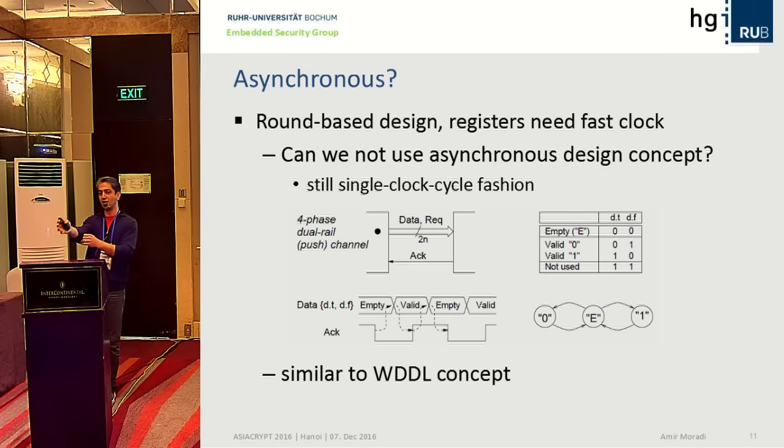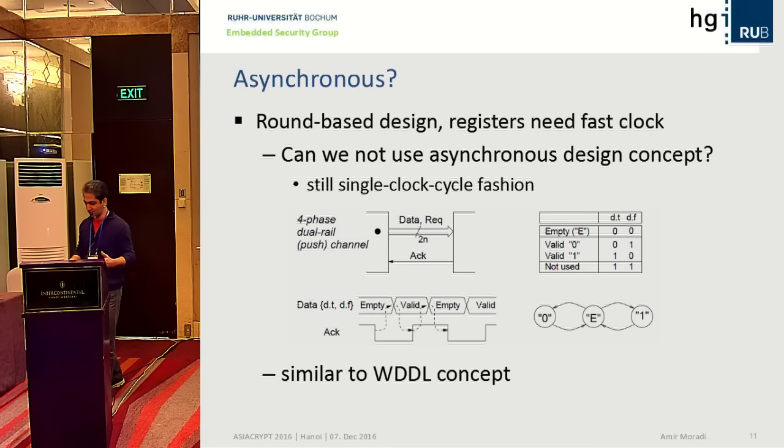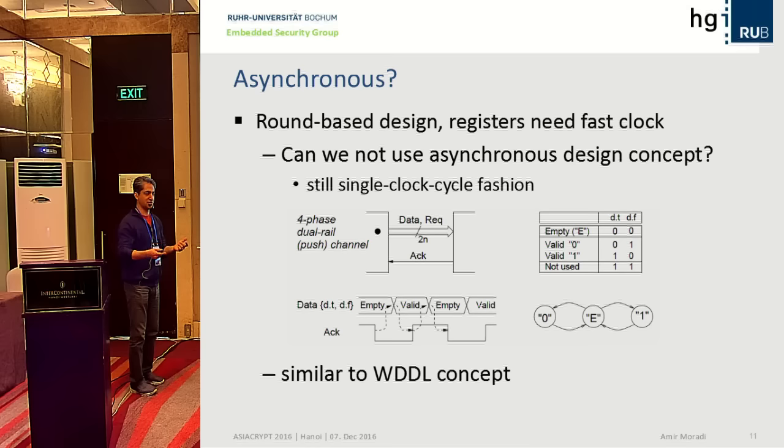And some kind of an evaluation waveform, which is cascaded through the whole circuit, and then the gates actually do not have any glitches, and then you don't need, in theory, to put registers in your design. It means that all the gates are completely glitch-free, and then you can implement the whole design in a loop way, and when the computation done by the design is finished, it will give you a signal that the computation is done.